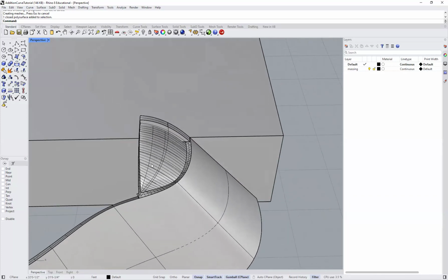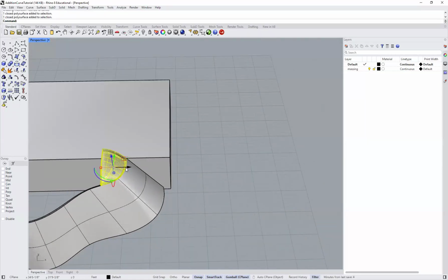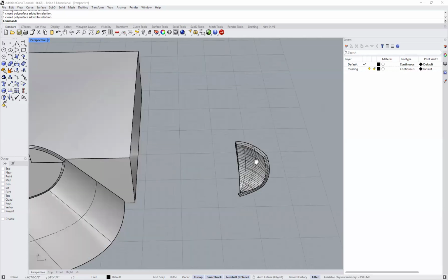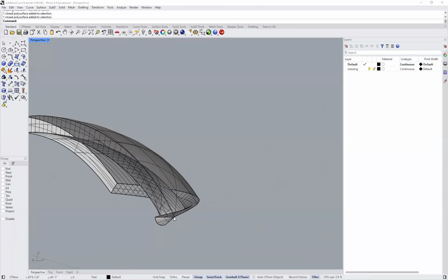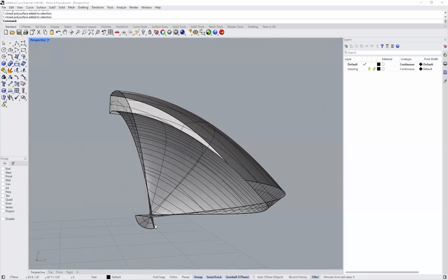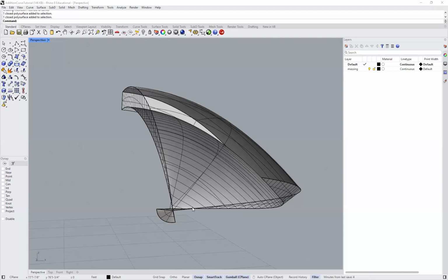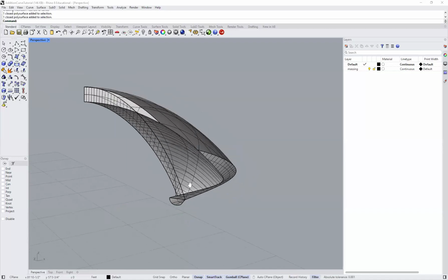Now, part of that has to do with the way that the surface was created. So if I pull this out, I'm going to click and move this out 25 feet. Okay. You'll notice something really interesting here, where right here, the surface kind of flipped on itself, right? And that's because it had all these points, and when you did the offset inward, some points went in kind of in that direction, while other points went in the opposite direction. So it's just kind of flipped on itself.